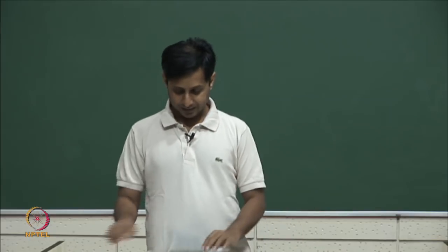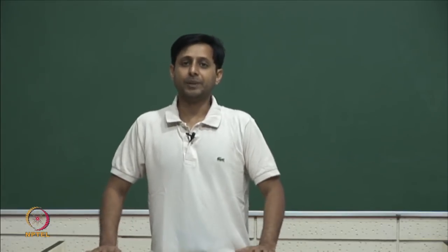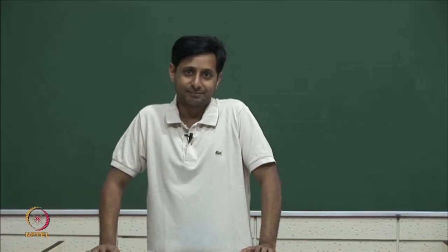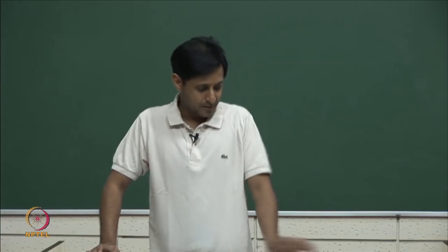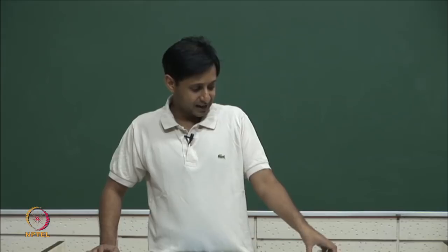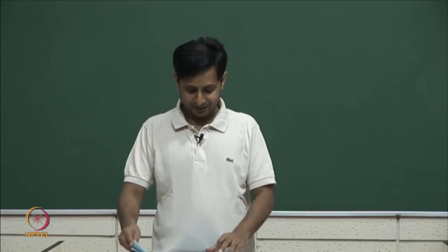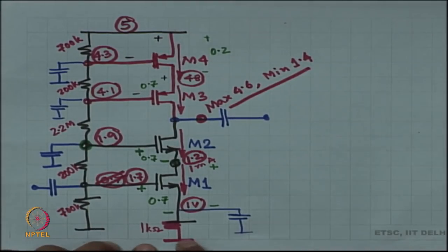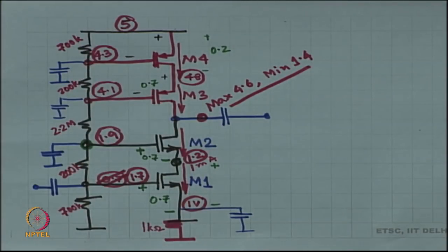All right. Now, we want to make a current source, for reasons that are not very obvious to you, but let us say I want to make sure that in this circuit I want a fixed bias current of 1 milliampere. Instead of having this resistor over here, I would place a current source pulling 1 milliampere down this entire circuit. Okay. So, that is probably my objective.